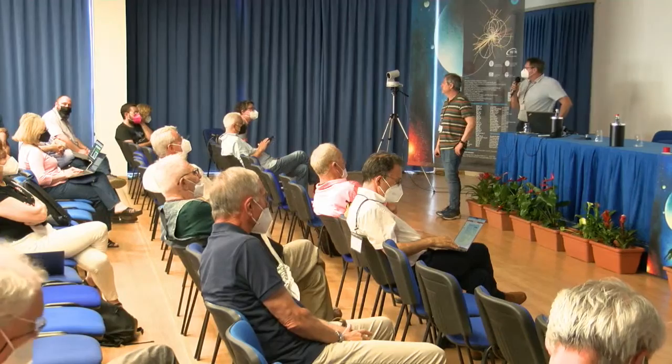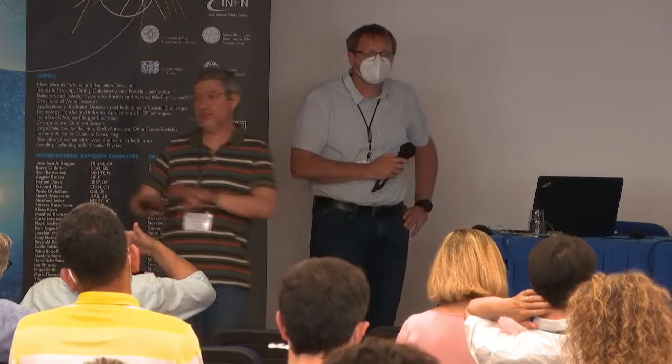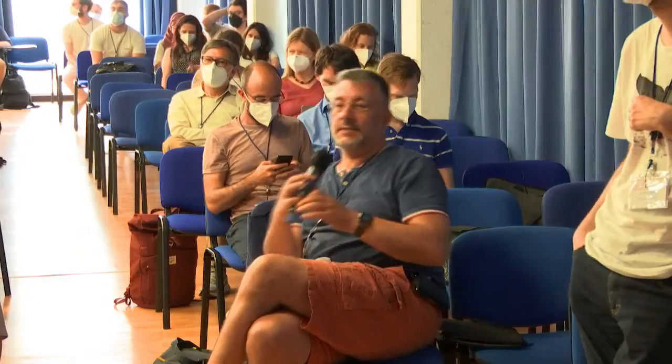It's time for questions. Sure. With your interpolation mode, you have like one interpolation step, right? So you can kind of double the interpolation. On the other hand, you have this time over threshold where you can actually count how many clocks you are over threshold. Can you combine these two so that you can interpolate not with one step, but with several steps, just by counting the pulse height in the neighboring pixels somehow? That's a good point. In principle, we could, but not with the present chip. So in the present chip, the two modes of operation are exclusive. You cannot do both things. Okay, thanks.